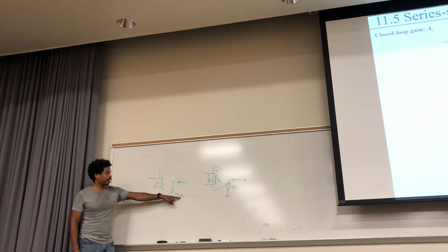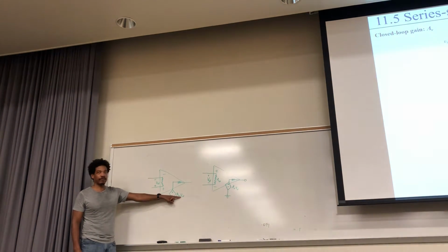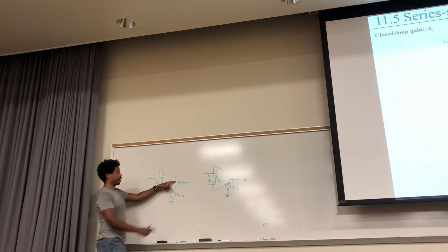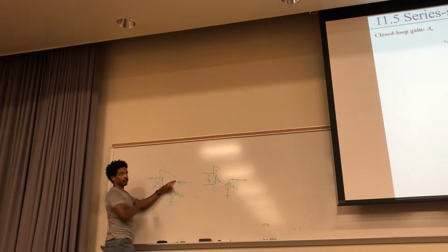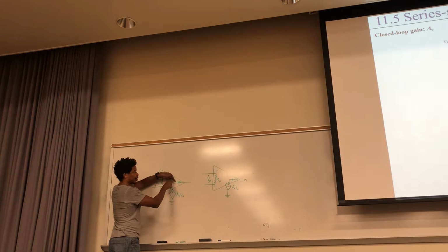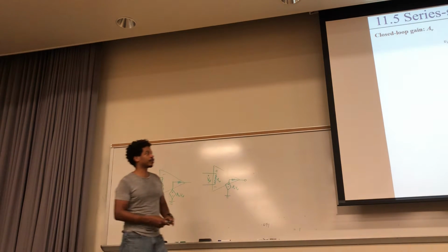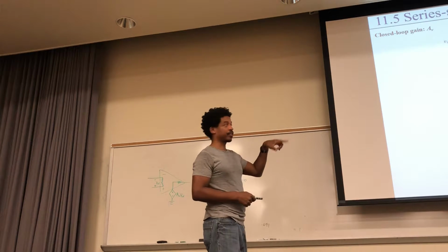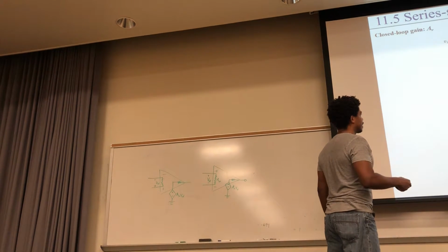This voltage, if that was negative, this voltage here is lower than this, because it's going uphill a negative amount of voltage, and it's starting at 0. So if it's going uphill some negative voltage, it's going to be negative. Depending on how negative this is, or how positive this is, will dictate what direction of current goes through that resistor. Okay? So if this voltage right here is negative, and that's more negative, then you know the current's going to go this direction. If this voltage is negative, and that's less negative, the current is going to go that direction. Or if it's positive, it's going to go that direction. Okay? So anyway, the reason I'm pointing it out is because that makes a difference in these calculations here. Okay. So anyway, we actually found this last time.